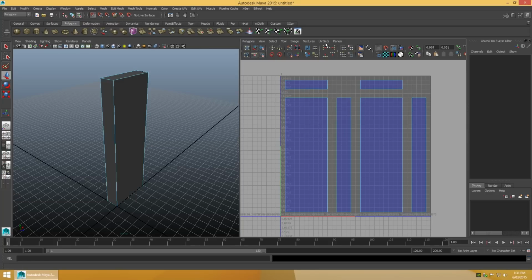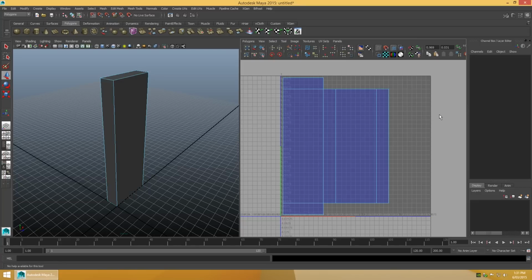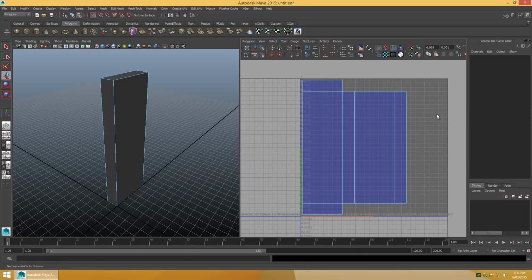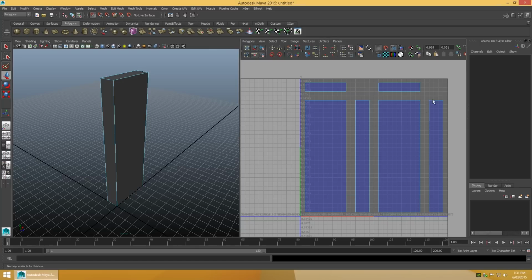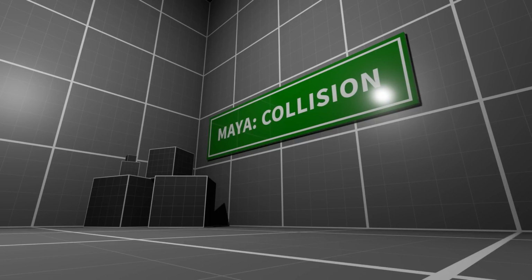At this point, the UV mapping for the Lightmap UV channel is complete. Switching between the two UV sets, the contrast in UV mapping considerations is evident. For the diffuse UV channel, there is a singular UV shell with uniform scaling that isn't snapped to the grid, whereas for the Lightmap UV channel, there are multiple UV shells with non-uniform scaling that are snapped to the grid.